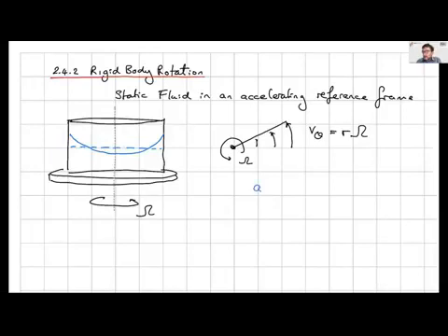And we already know that the acceleration in a rigid body rotation, which would be the same as the time rate of change of the velocity following a material element, is that as I move around in a circular motion here, I'm changing my velocity. And so the acceleration we've already worked out in the past is given by v theta squared over r, and it's inwardly directed. So it's in the minus e_r direction, and that's the direction of the acceleration.